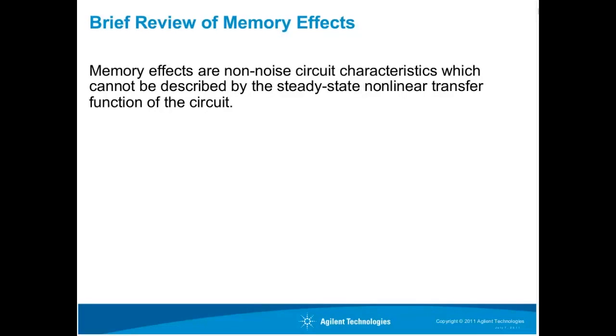So what am I saying? I'm saying if you build a steady-state transfer function for your circuit that represents its nonlinear behavior, everything that you didn't model we're going to call memory effects except for noise.